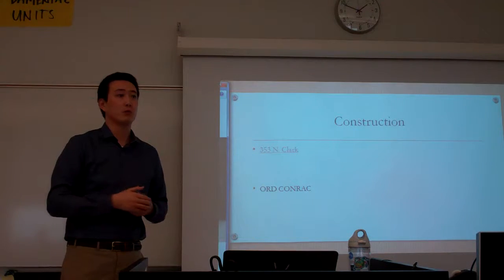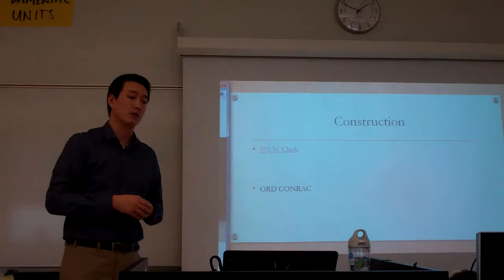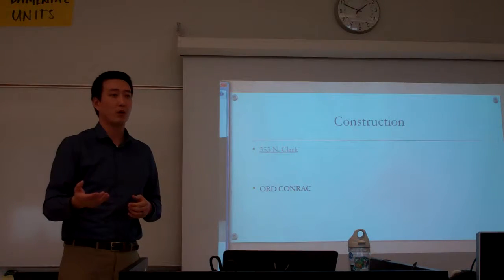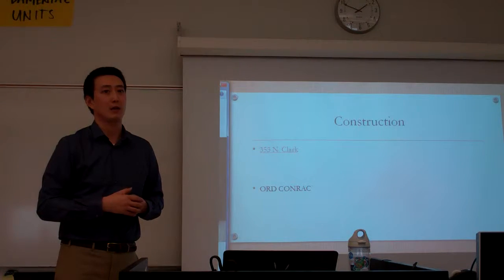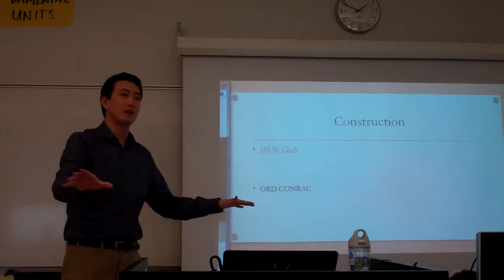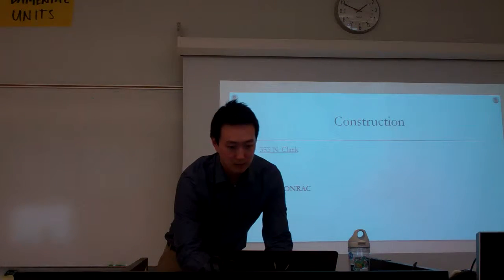So that's what we do. We have to keep it warm for health and safety reasons, and if we're doing a concrete pour, we have to do that under certain temperatures. So we have to maintain that if we're doing it outside. We put mats on top or whatever. So that's that.